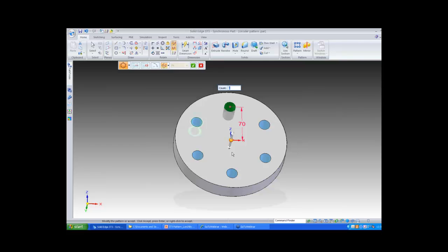What if I don't want the whole circle? I want these instances to line up to a specific arc. What you can do is there's an option here where you can toggle from circle to arc or from arc to circle. So in this case, I can toggle, and then I can just enter a value for the angle. And right now my instances span 240, and the angle between them changes from 60 to 40. So similarly, you can just make it a little smaller or bigger.